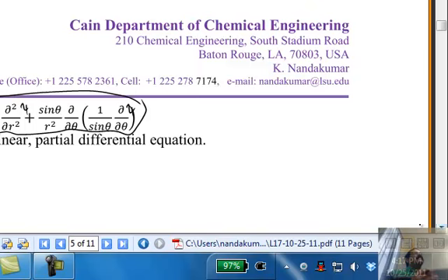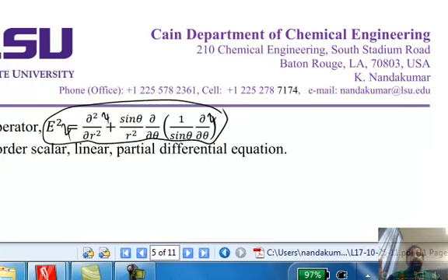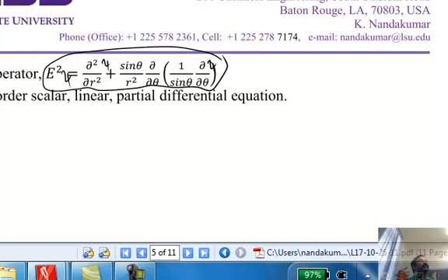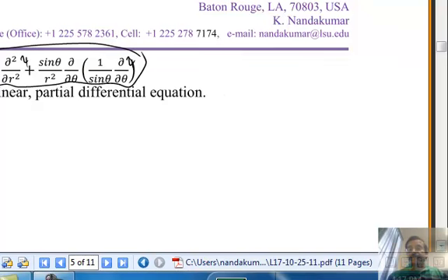What have we done so far? We took the Stokes equation for a spherical geometry and imposed axis symmetry, got the 3 equations, 2 momentum and 1 continuity, and we eliminated the pressure, eliminated the velocities, and got a single equation in terms of the stream function, a fourth order equation. But we wrote down the boundary conditions in terms of VR and V theta. If you're going to solve the stream function equation, we need a boundary condition for psi, the stream function. So how do we get that?